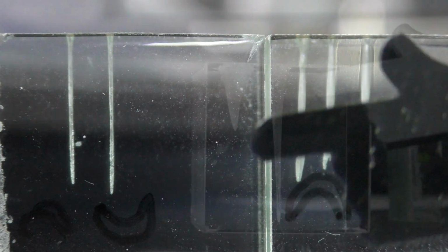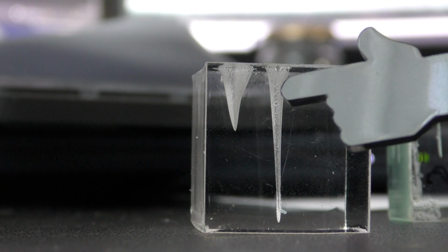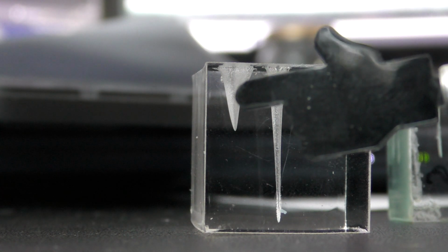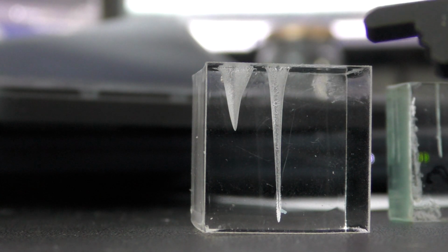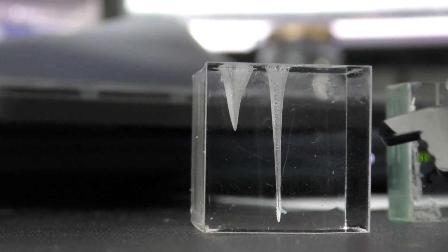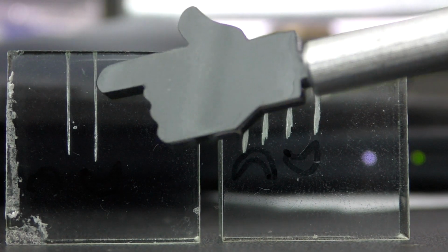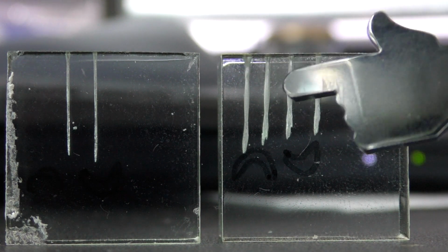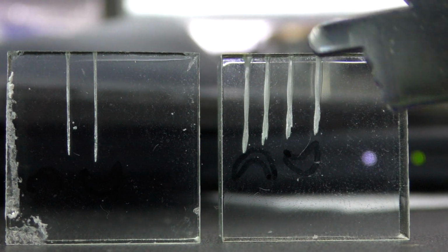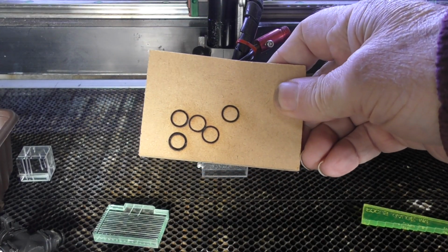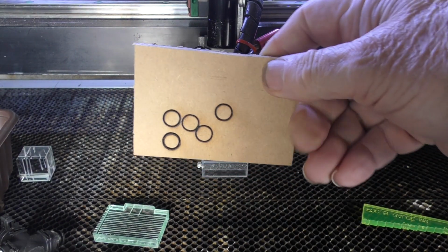larger diameter beam. I mean, there's our 30-watt naked beam, and then we move to where the beam starts to grow here, and it grows from 3mm to about 6mm. Look what happens to the penetration. This is just confirming what we're finding. If we can keep the beam small, we get better penetration. Here, the beam is big to start with, and it's not penetrating as deeply, even though there's twice as much power there. These tests are not performing as I expected.